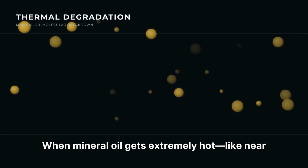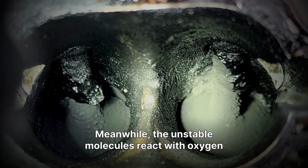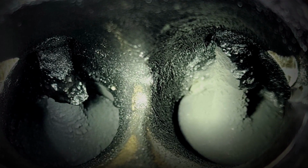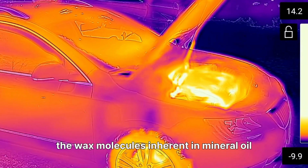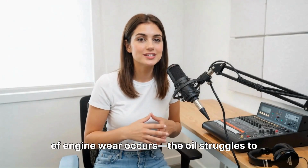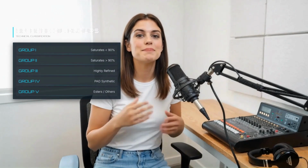When mineral oil gets extremely hot, like near the exhaust valves, lighter molecules evaporate, leaving behind a thicker, sludgy fluid. Meanwhile, the unstable molecules react with oxygen and heat to form carbon deposits and varnish. This is thermal oxidation. On the opposite end, in freezing temperatures, the wax molecules inherent in mineral oil begin to crystallize. The oil thickens up. This means during a cold start, when 75% of engine wear occurs, the oil struggles to pump to the top of the engine.